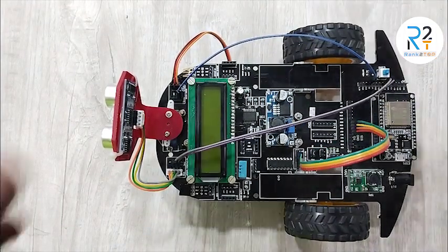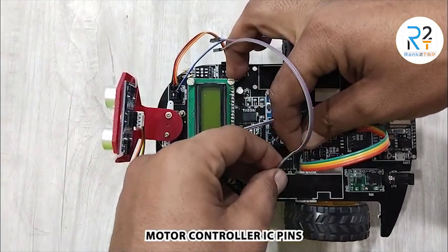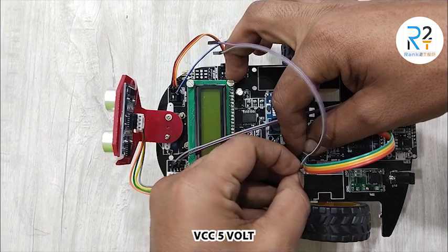Connect also the EN1 and EN2 motor controller IC pins with VCC 5 volt.